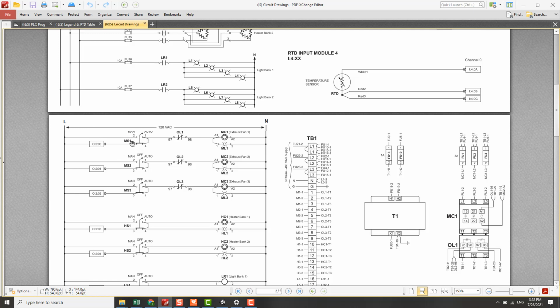So what we can do is we try to measure the voltage at this point 3 of the motor selector 1. Okay, this is a live AC. So the AC current actually sourcing the PLC output switch module 2 channel 0, and then sync the external output load to the ground or common point or neutral. Okay, we put the multimeter black probe at the neutral or ground side, and then put the red probe at this point 3 of the motor selector 1.